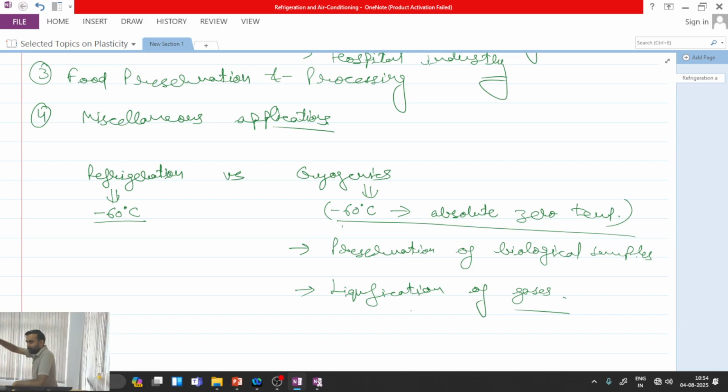You need to keep on cooling the air. At one point of time, liquefaction temperature of one gas will be coming. You cool further, you separate that gas. Now you have only two gases in the mixture. Go to further below temperature. Second gas's liquefying temperature will be achieved. It will be liquefied. You will be having the third gas. If that is also required in liquid stage, then you have to further decrease the temperature.